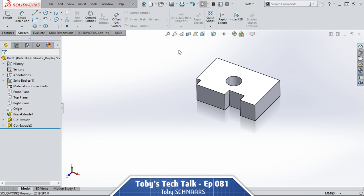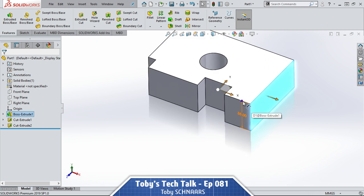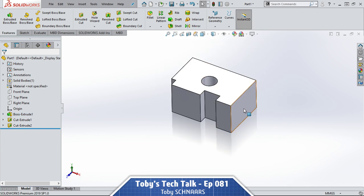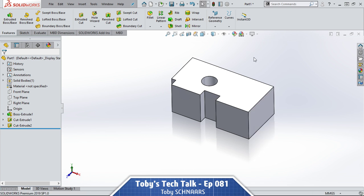Okay, similarly, when it comes to feature mode, if you have Instant 3D on, you can click on a feature and you can grab a dimensional value and drag it to change that dimensional value. You can also single click on the dimension to change its value. Just a matter of preference. I usually have it turned off. There's times when I turn it on temporarily, like if I want to do some push-pull of the geometry, I'll turn it on. But for the most part, I have it turned off.